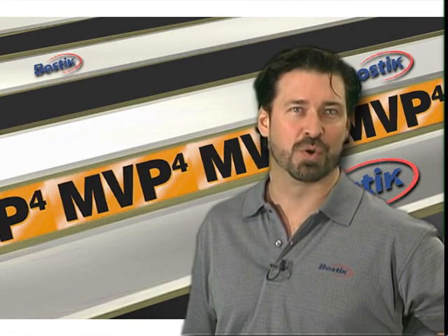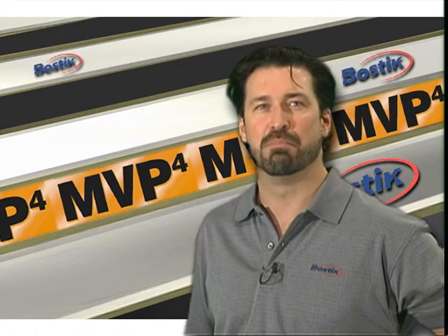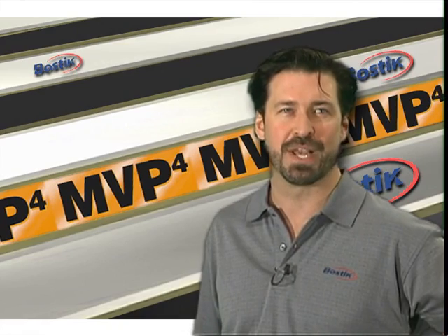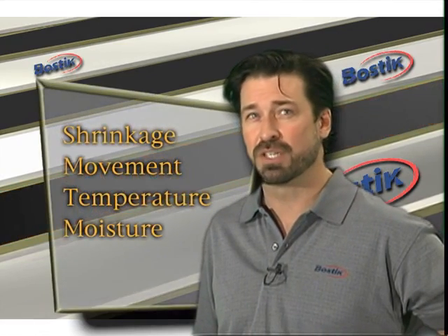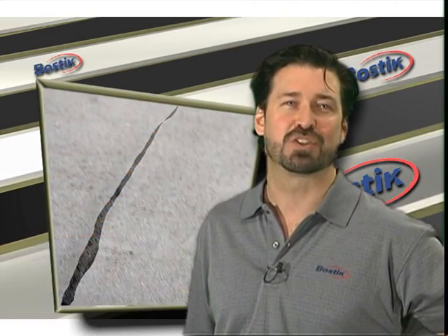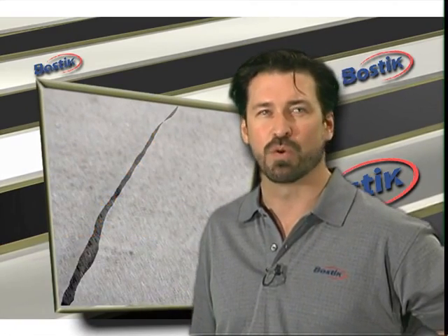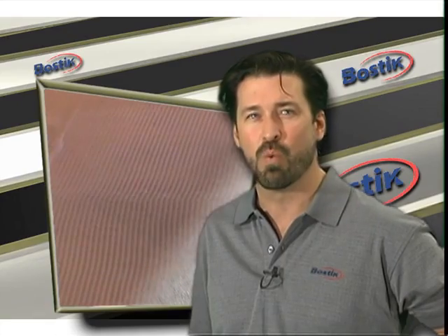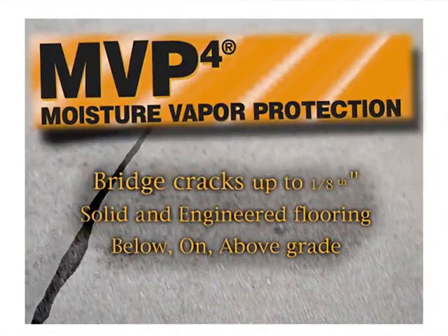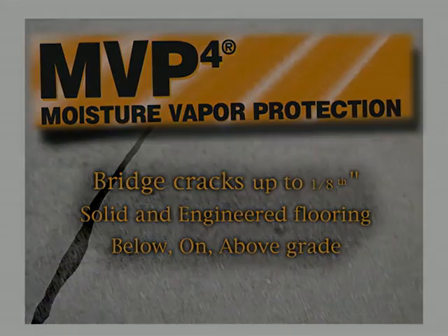When used over concrete, MVP's anti-fracture membrane ability can be extremely beneficial to the constant dimensional changes in a slab caused by shrinkage, movement, temperature, and/or moisture. These changes may lead to unknown random cracks or fissures in the substrate surface well after the flooring is installed. MVP4 will bridge gaps up to 1/8 of an inch beneath solid and engineered wood flooring when installed below, on, or above grade, according to the directions.